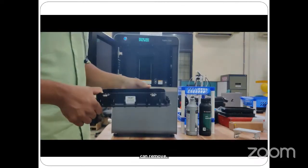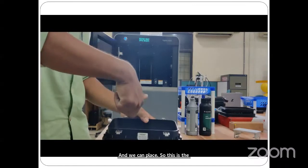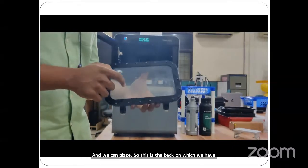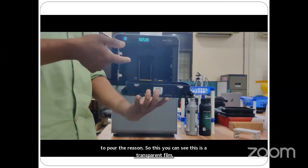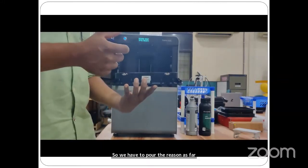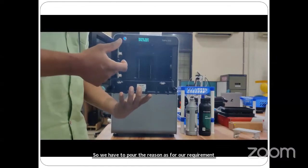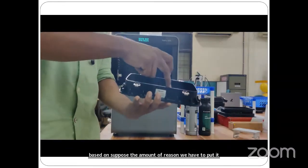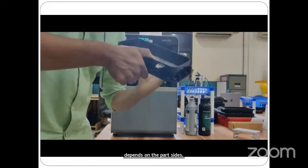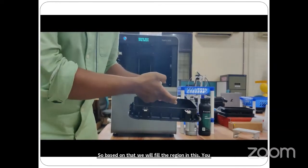This is the vat on which we have to pour the resin. You can see this is a transparent film. We have to pour the resin as per our requirement. The amount of resin depends on the part size, so based on that, we will fill the resin in this. You have an indicator up to which level you have to fill.